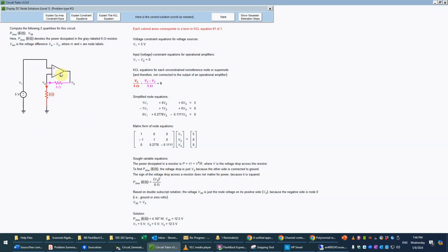non-inverting amplifier, where we have this type of configuration where the input voltage is connected to the positive terminal, and then we have a feedback resistor and then a resistor to ground. The formula for that, derived in the introductory tutorial, is just the gain is 1 plus 9 divided by 6, which is 3/2, or 1.5. So that plus 1 is 2.5 is our gain. And again, multiplying 2.5 by 5 will directly give us the V3 value that we went through all these equations to get. And that's just going to be 12.5. So we could have just entered that at the very beginning and saved us all this trouble.